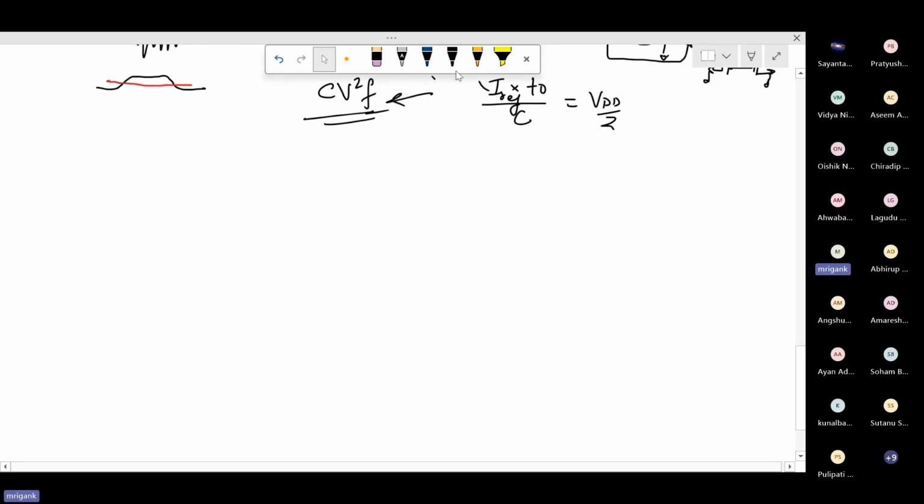So another variation, I can give you one higher level thing that people have done. They don't stop at time domain processing, they go for frequency domain processing. So there will be an amplifier A. After that, they will go for A to D, that means ADC. This ADC will give you a high precision recording of that signal, a digital value.